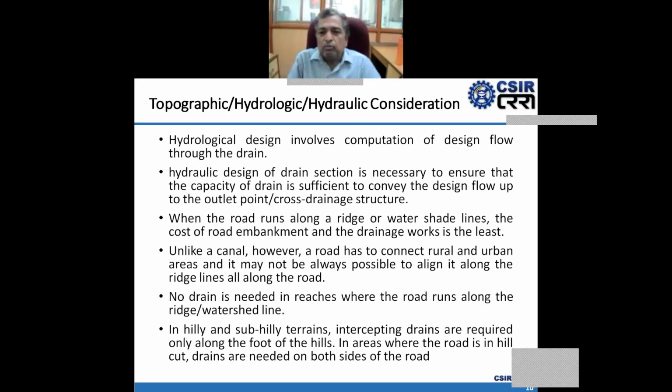Hydrological design involves computation of design flow through the drain. Hydraulic design of the drain section is necessary to ensure that the capacity of the drain is sufficient to convey the design flow to the outlet points, culvert or cross drainage structures.